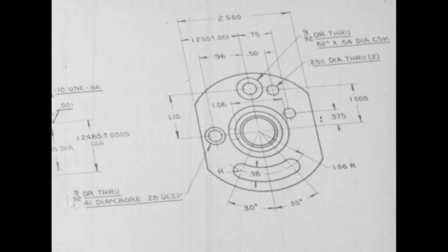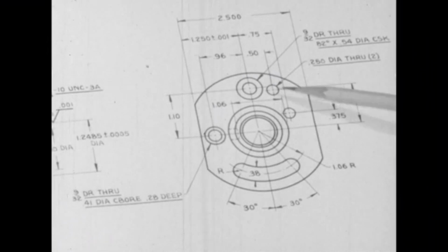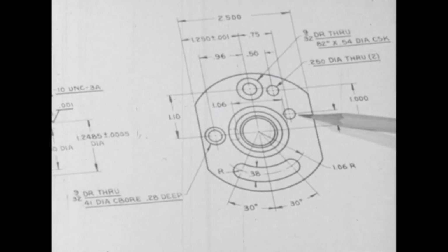The milling machine table with the workpiece may easily be relocated for drilling these holes, because in the present setup, the relationship between the workpiece center and the milling machine spindle center is known.